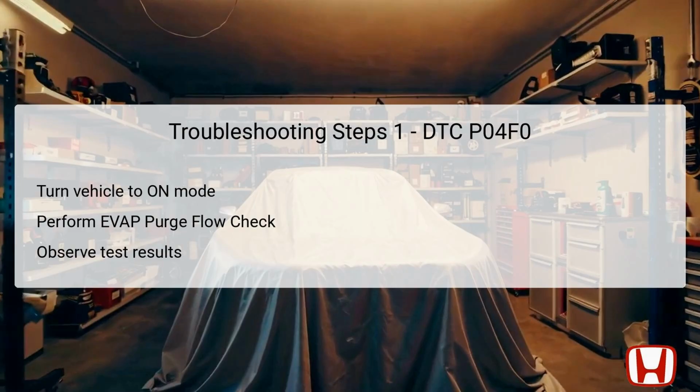The initial step in troubleshooting DTC P04F0 requires the technician to turn the vehicle ignition to the on position without starting the engine. Following this, the Honda Diagnostic System, HDS, should be accessed to perform the EVAP purge flow check test.